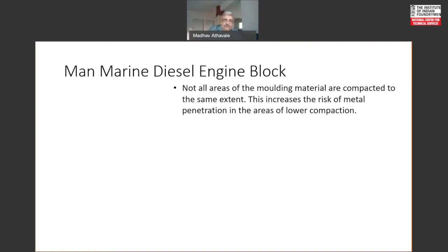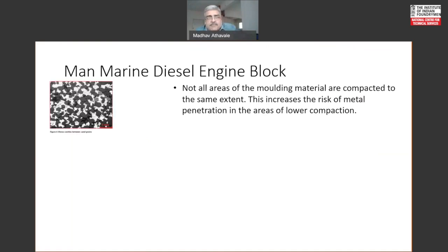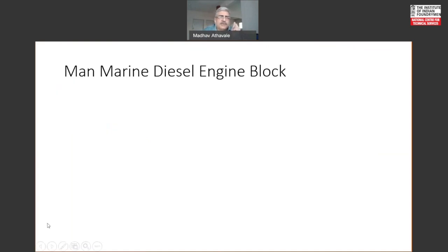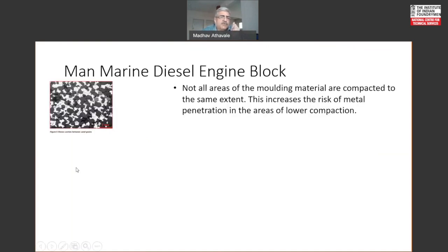So if you don't fill the mold in the correct time, then as the bench life starts going off, the flowability of the sand becomes an issue. So packing will become a problem. And here is a picture, as you can see, of how the open surface looks like.